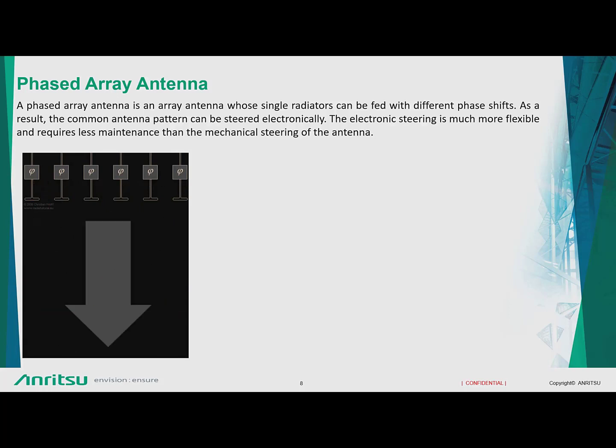So what you see from this particular image is the fact that if all the phase shifters are at an angle of 0 degrees, then the beam is just looking at the forward direction. But the moment I introduce a phase shift between these elements, you can say them elements because these are basically antenna elements. If I introduce a phase difference, then this beam can be steered into another direction, and this is what normally happens nowadays with the radar systems, and in fact, for that matter, the 5G base station antennas that you are seeing. This is the basic principle.